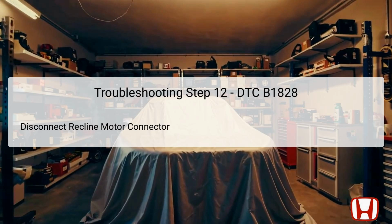This step is vital for isolating the recline motor from the control unit and testing the electrical pathways to ensure they are functioning. Ensure a firm grip on the connector with no lateral force applied to prevent pin damage. This disconnection allows you to assess electrical continuity between the connected components without interference from other signals or circuits. It is imperative that this step is executed while the ignition is off to maintain safety. Isolating each component effectively directs attention to possible faulty parts in the circuit, heavily facilitating the troubleshooting process.